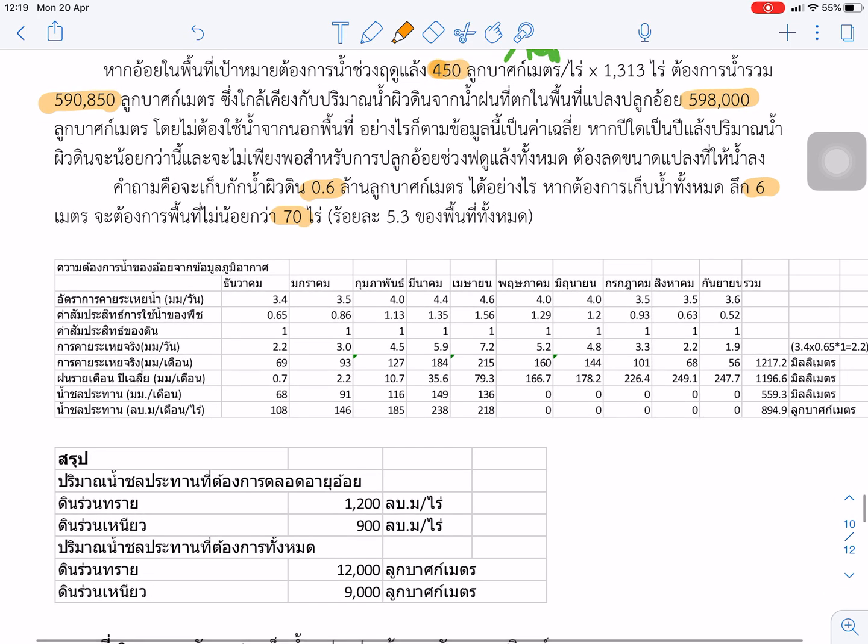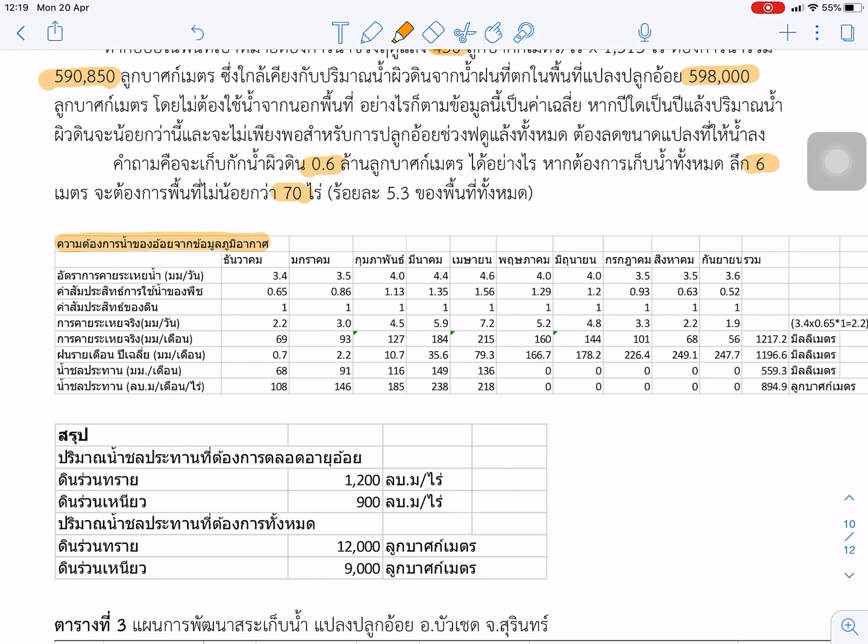And this table you have done already from lecture 7 to estimate the water requirement for the sugarcane. It is from the crop water reference. The first row is the crop water reference in millimeter per year, and we multiply by the crop factor, soil factor, and can estimate the actual evapotranspiration, and subtract the monthly rainfall, so we get the irrigation water demand.